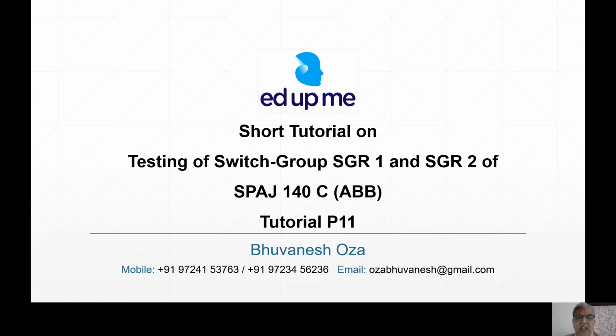Then SGB 5 was giving a very important function, that is double setting groups, two setting groups. You can have two current settings, two time settings, two high set settings, two different characteristics, everything double, everything twice. Yes, because the power system will be changing.